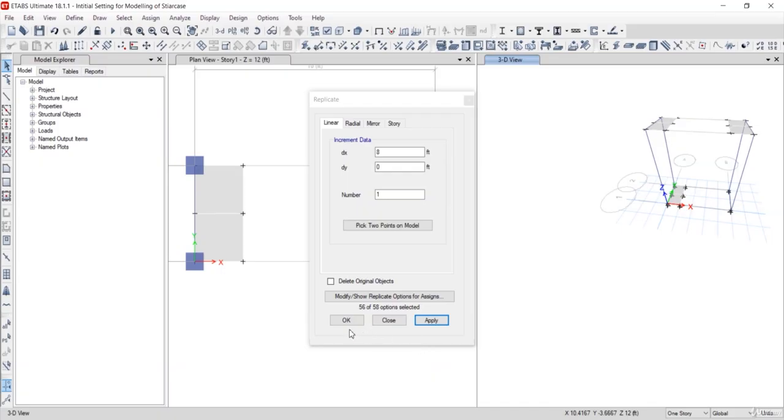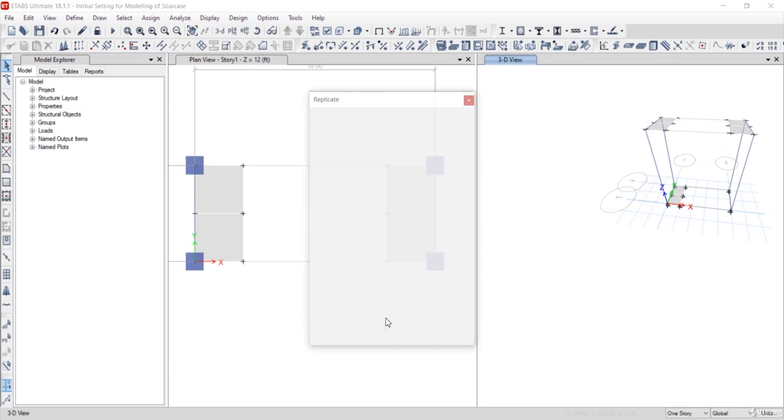So before clicking on OK, I will suggest, we want to make this mid landing slab at the mid of this one. Okay, so for that let's close this one. Or what you can do is you can copy the same here in this region, but you can see here that we don't have this option. Okay, we don't have a copy option in this side direction, so for that we have to close this one.